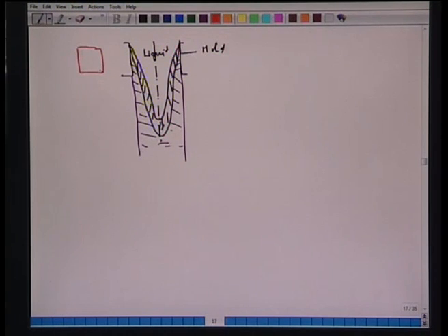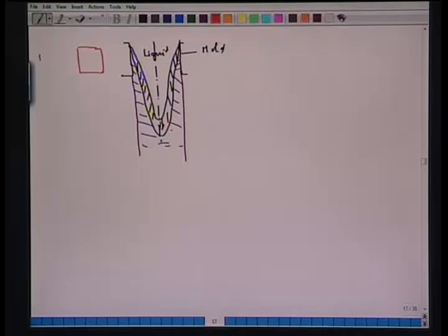You know, electromagnetic stirring is a non-contact type of stirring method. That means you have to install an electromagnetic stirrer somewhere outside, and from here a magnetic field will be created in the liquid, and that causes stirring. So it is a non-contact type of stirring mechanism. So one can install an electromagnetic stirrer here. So this, let us say, is mold EMS.